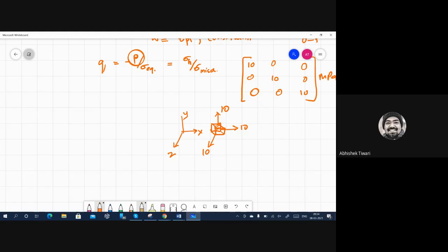And this represents hydrostatic tension. So this thing, as a response to this, is going to get expanded volumetrically. So there will be a volumetric strain. The opposite of this is what Abaqus calculates. So the pressure is positive. The pressure is a positive value when it is compressive in nature. So it's exactly opposite of what is happening here.